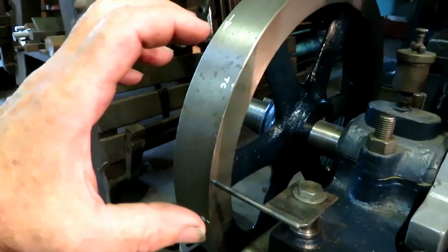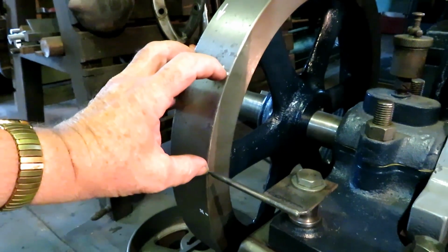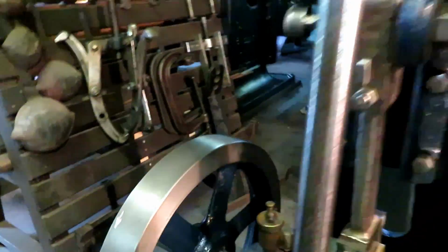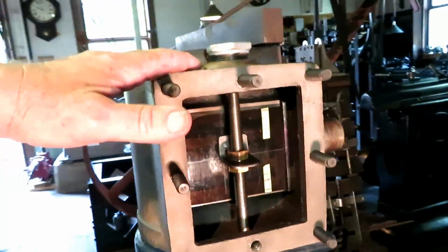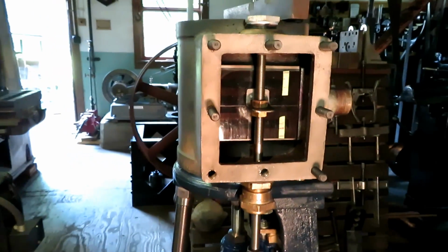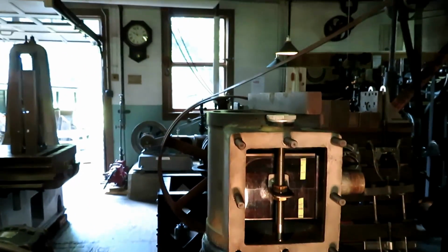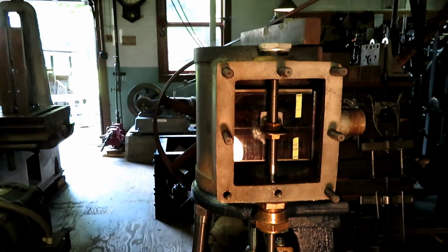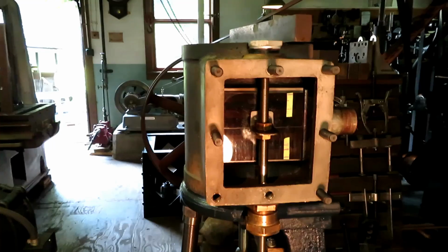The exhaust is closed off, and that steam is trapped in there. And for that distance, it's compressing the steam in the top part of the stroke and cushioning the piston and the rod and everything that's traveling up from coming up against the top, and it makes it a lot easier on the components. All steam engines are designed with a certain amount of cushion in there.